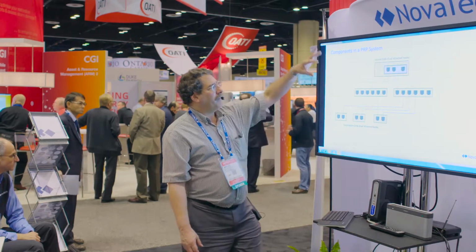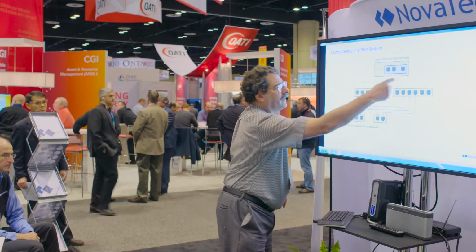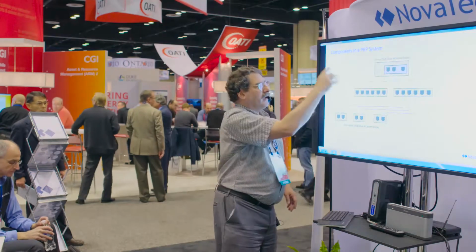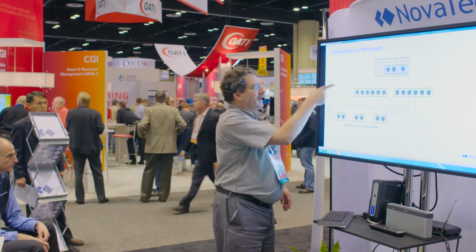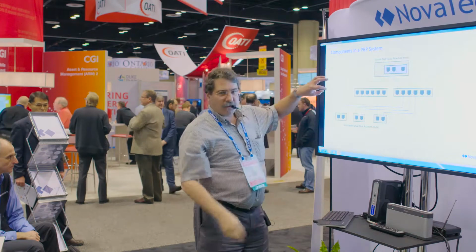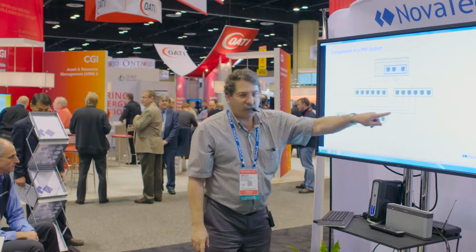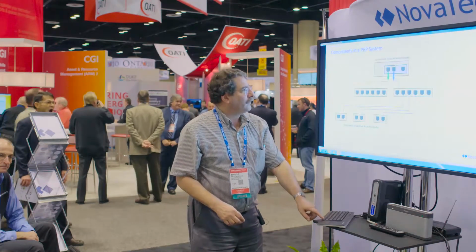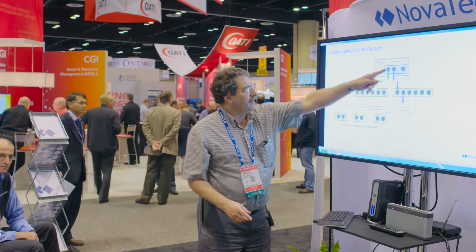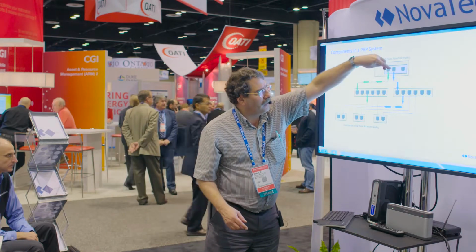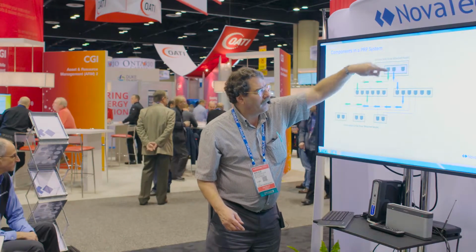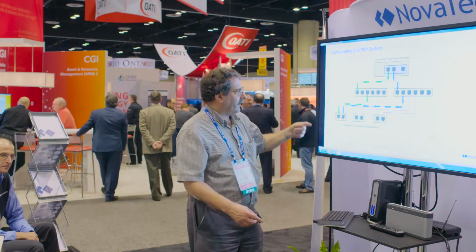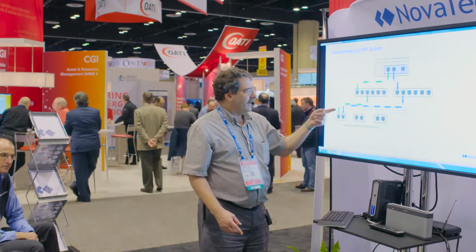So this shows you how a PRP system works. Imagine this switch here is actually an entire switching infrastructure. The idea is you keep them completely separate. You take each of these infrastructures and power them off their own power supply. You take each of these wires and make sure they're physically separated. We get a source of information coming from here. It comes out of both of these ports, goes into the switching infrastructure, gets to the destination, and the first one that gets there wins.